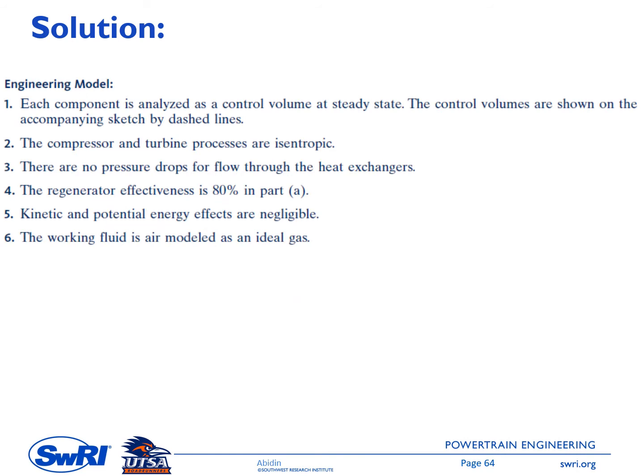These are the assumptions of the engineering model. Each component is analyzed as a control volume at steady state, and the processes inside the compressor and turbine are isentropic.